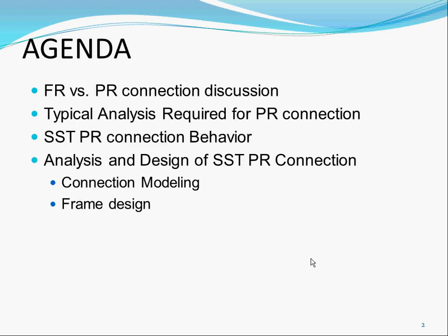Typically, when you do a moment frame connection and model it in SAP, people just stick in a line for a beam and a line for a column. Where it comes to the connection, they just connect it and don't release any shear or any moment. So they're just making a moment connection, and that's all they have to do. Because that's considered rigid, the connection has not much rotation due to bolt slip or whatever.